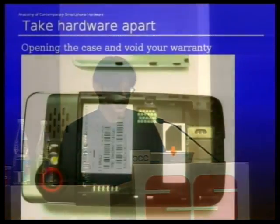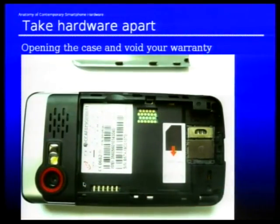So how do you go about this? Opening the case and voiding your warranty is obviously a nice thing to do. Warranty labels you can always find on eBay and somewhere else on the net. So, yeah. This is the battery removed from the device. And as you can see, there is already some kind of connector here, or test pads. It's not really a connector, but test pads. And if you see test pads that are accessible from the outside of the device, then you can be sure there is at least a serial port and or the JTAG interface of the application processor on those pads. You just need to figure out which one is which.